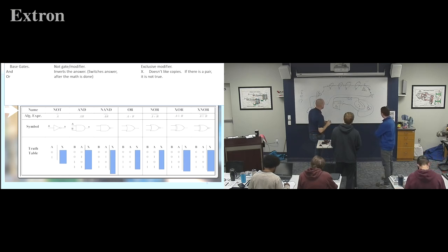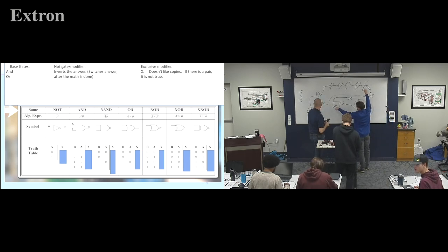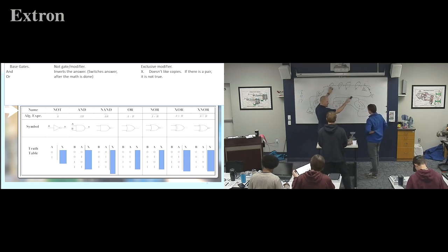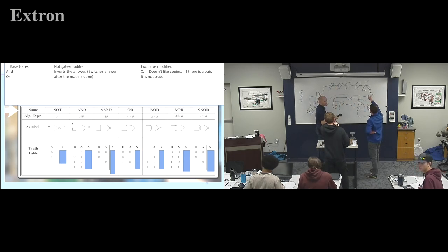Parker has a question. I guess I'm just getting confused because it feels like if you have an open switch and use your voltmeter, you get 12. But then when you close it and you measure it, you get 0. Yep, that's correct. The reason I went wrong is, if I have no amp drop, I'm not gonna have a voltage drop across these light bulbs. Okay, so you still have the pressure. You still have the voltage in the system. Yeah, the pressure's still there, but I'm not losing any. And that's why we use that word voltage drop. I don't drop any voltage.